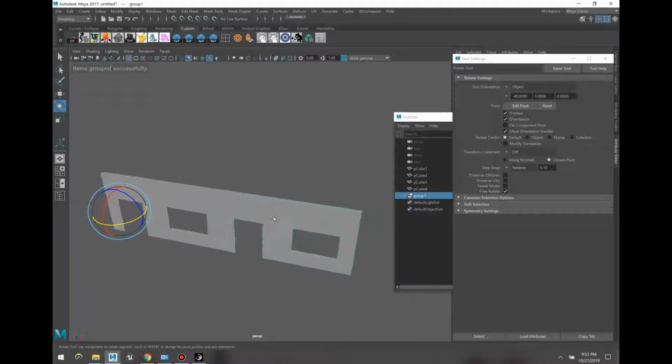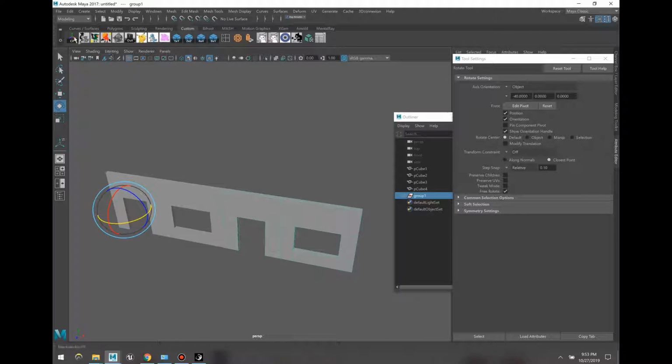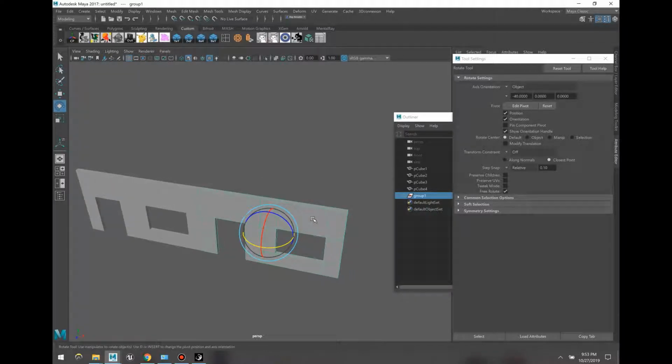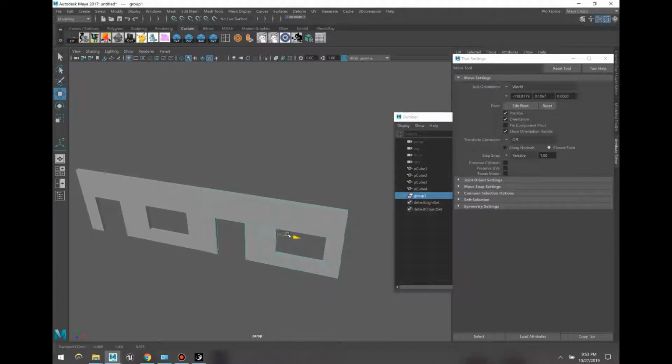and then like that, the pivot ends up always at 0. And now if I go here to this hotkey, I'll hit center pivot, so it'll center the pivot. But then I can also hit insert, if I could find that on this laptop. Here. Yep, if I hit insert, I can now edit the pivot point.